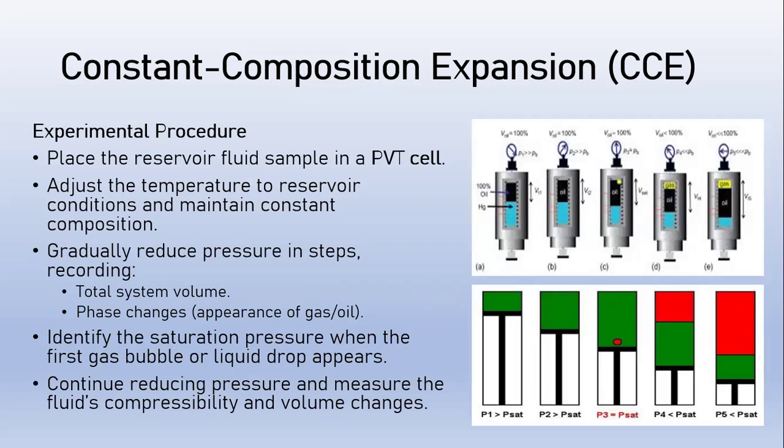So the experimental procedure is, after collecting the fluid sample from the field guys, you put it in a PVT cell and subject it to reservoir temperature and reservoir pressure. How do we do this? Subjecting it to reservoir conditions.